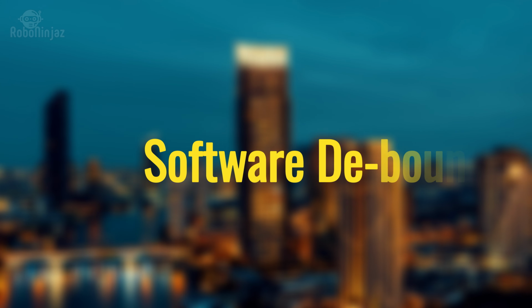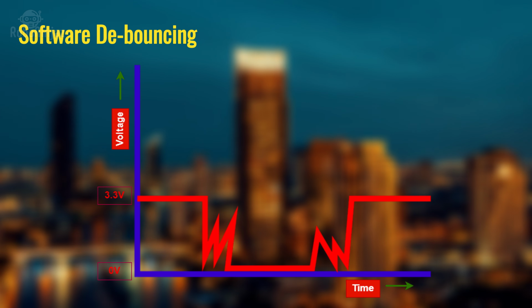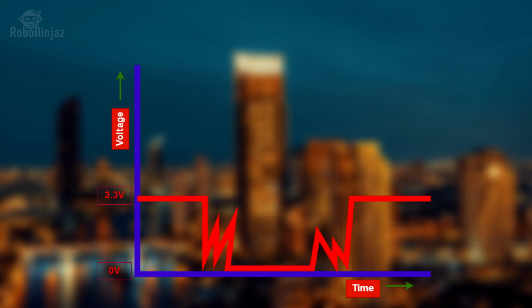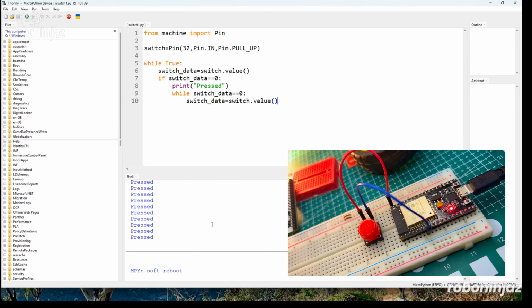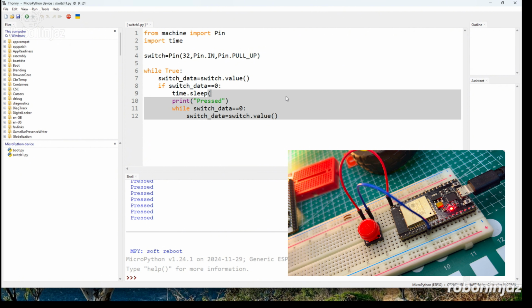Now let's implement the software debouncing method. If you look closely at the graph, you'll notice that the spikes happen only during the transition, right when the switch is pressed or released. In the other areas, the voltage remains stable. So, to tackle this in code, we'll simply add a short delay right after we detect a switch press. This delay gives time for the bouncing to settle down. By the time the delay ends, the spikes are gone, and we can safely confirm the button press.